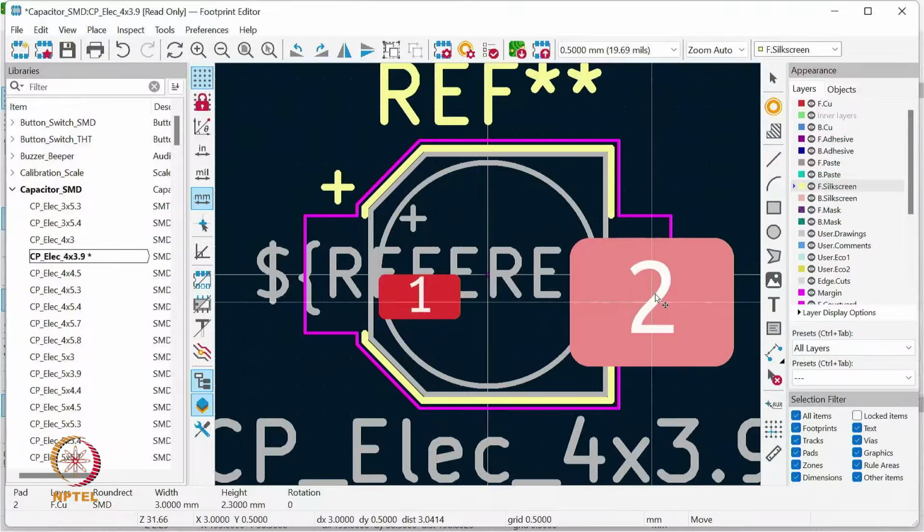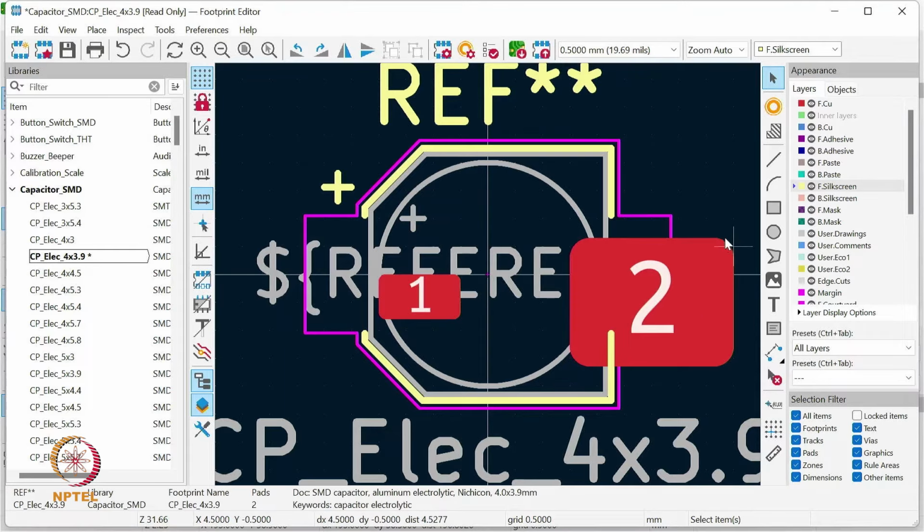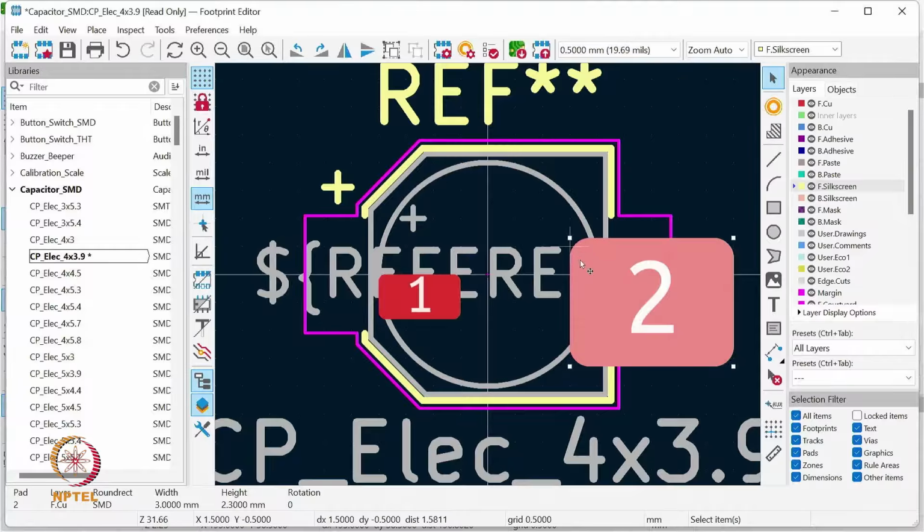So I can change these pads like this. It's like paint and brush. We can edit anything, we can write any text here for our understanding. We can update this footprint to suit our requirement. This is a very simple example of two terminals, where the capacitor has only two terminals. One pin is the smaller one, one pin is the bigger one, so we can edit our footprint.